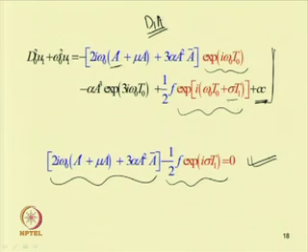So, when this sigma T 1 tends to 0, that means when this sigma tends to 0, only these terms will tend to omega 0 T 0 and it will be a secular term. So, if sigma is near to 0, then only these terms will be equal to 0 and it will lead to a secular term. That is why it is known as a mixed secular term, and this detuning parameter has to be taken in such a way that it will be in the neighborhood of this omega 0, that means in the neighborhood of the natural frequency. So, if the forcing frequency is very close to this natural frequency, then only we can take this term to be the secular term.